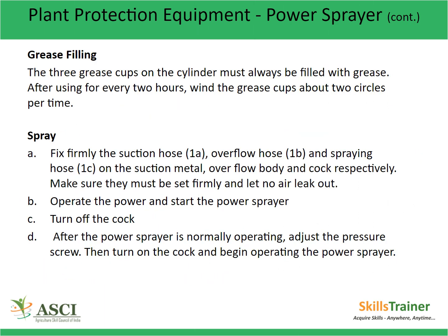Grease filling. The three grease cups on the cylinder must always be filled with grease. After using for every 2 hours, wind the grease cups about 2 circles per time.